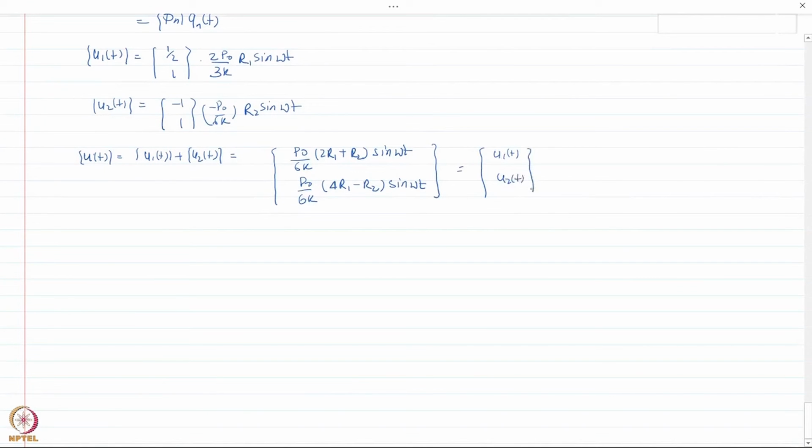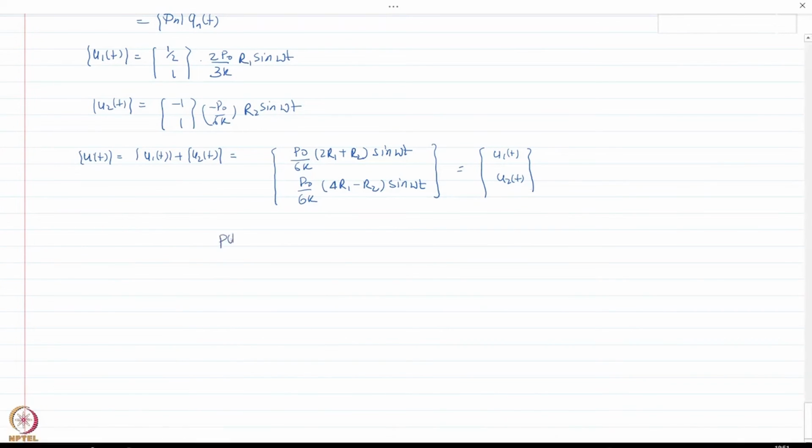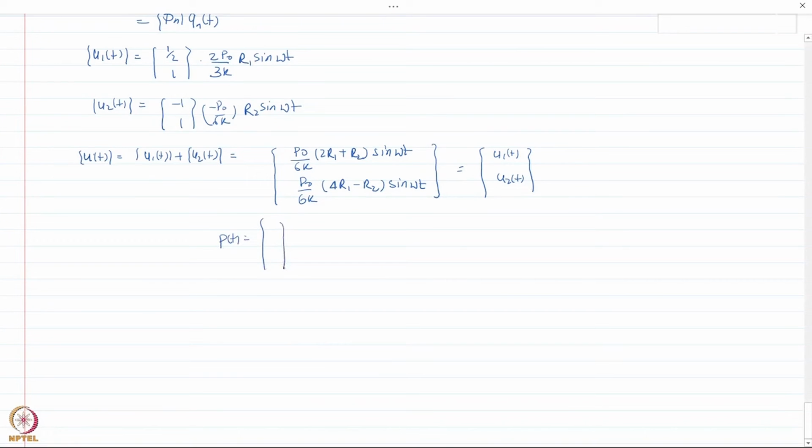All right. So we have seen that if the external excitation force is given, we can construct the force vector P(t), and then utilize the modal analysis procedure to find the response at each degree of freedom. This only focused on finding the displacement response.